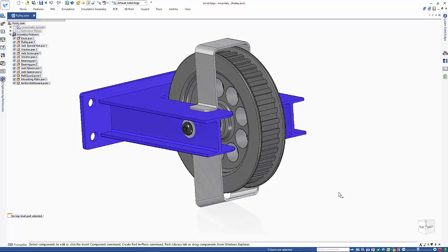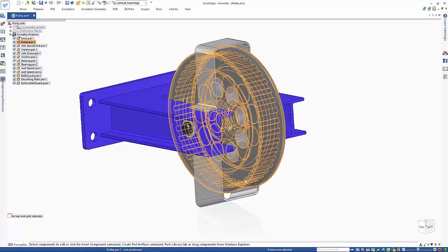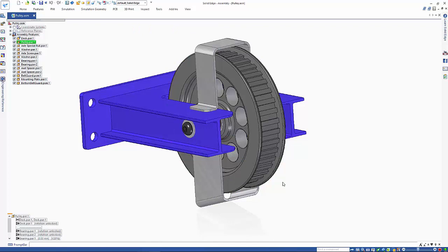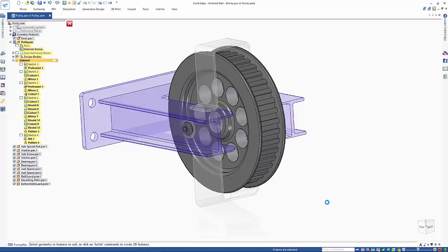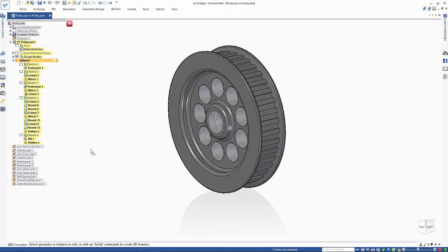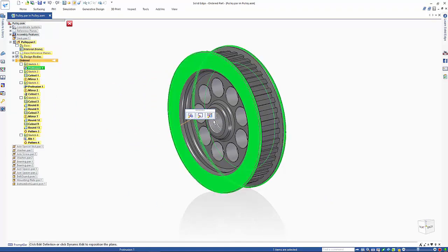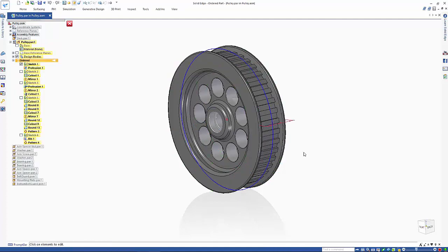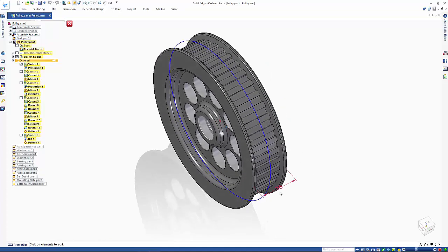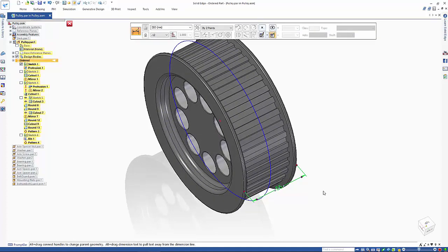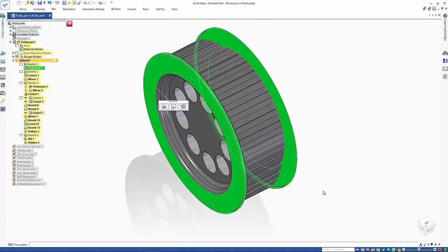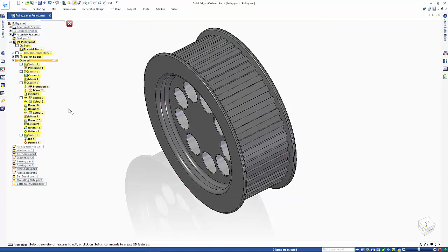First of all, let's approach this as you would in most any other CAD system using history-based editing. After we activate into the part file, you will notice the list of the features on the left. Since I need to make the pulley wider, we can easily select the side of the pulley to make the initial edit. We see there is an overall dimension of 35, which I can change to 55. That makes this easy, or does it?